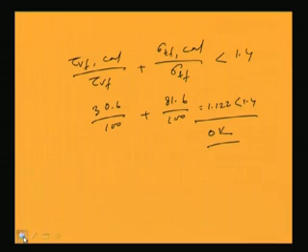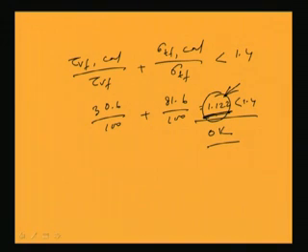Now, in the last step what we have seen is that the value is coming 1.122. If it becomes more than 1.4, then it is needless to mention that we have to redesign it. Redesign means we have to change the number of rivets, that is, increase the number of rivets. Depending on how much the value is coming, we decide whether 1 or 2 rivets or 4 will be added. It depends on how much more than 1.4 it is, and of course on the designer's experience also. So in this way we can make it.